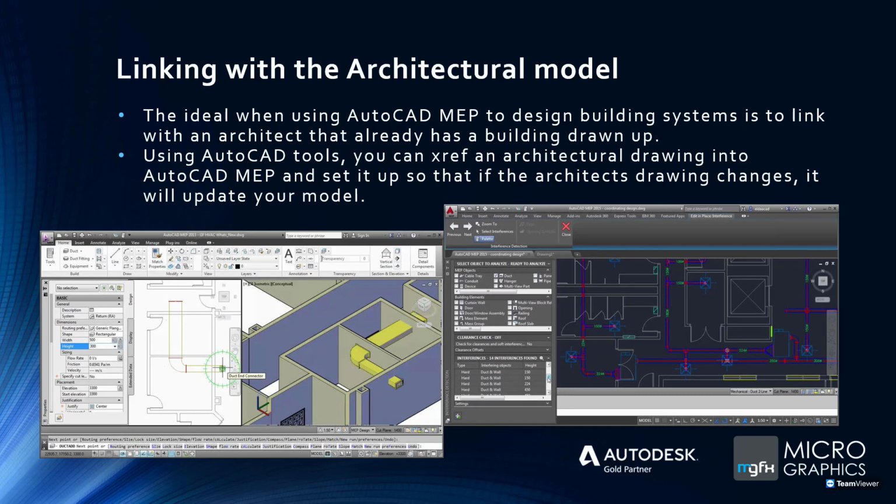If you look at it from the side, they will just be the 2D plan with the ducts floating, as opposed to the image on the left, where you have 3D components. And if you look at it from the southwest isometric, they fit in place. You can check clashes between the walls and the various things, whereas you can't do that in the 2D environment, because it's 2D plans versus the 3D ducts and services.